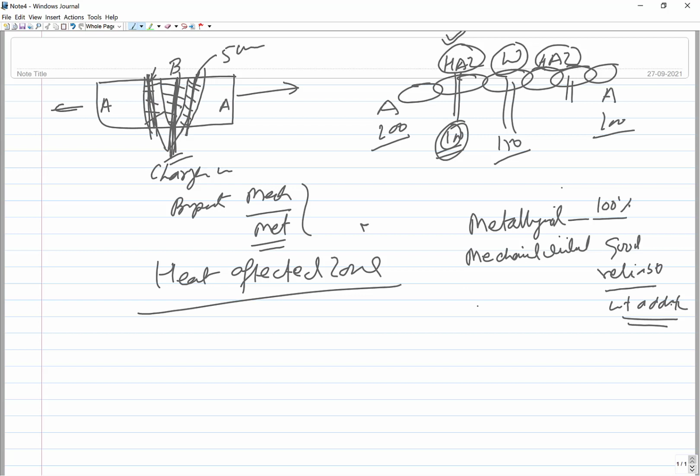On the other hand, lastly you have the physical and chemical interaction approach, where adhesive joints or chemical joints are developed. There, what we see in the case of adhesive joints and other chemical joints is that they are very weak. The joint efficiency may be just say 20 to 50% of the base metal.